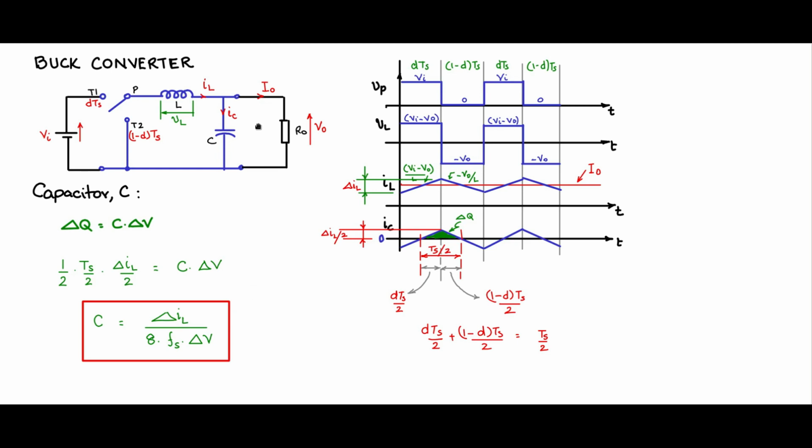Of course, in a practical capacitor, there will be ESR. The drop across the ESR will also come into the ripple. But anyway, we take here the ripple across the capacitor due to the capacitor action, which is given by I equal to C dVc by dt.